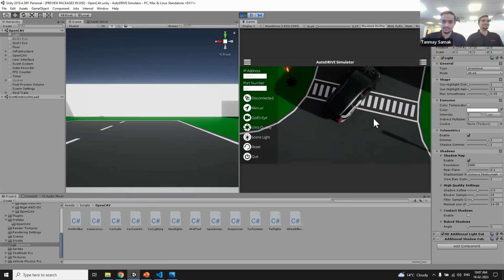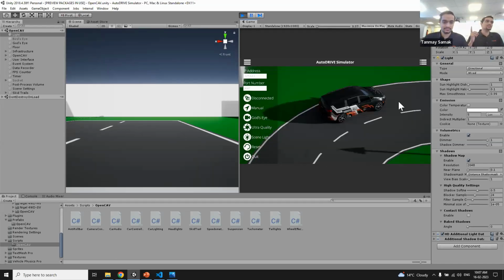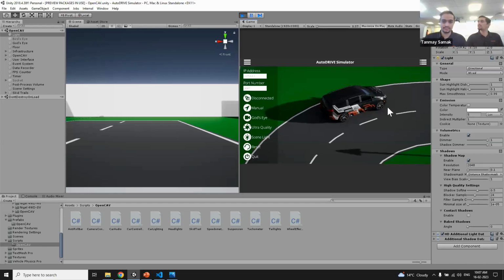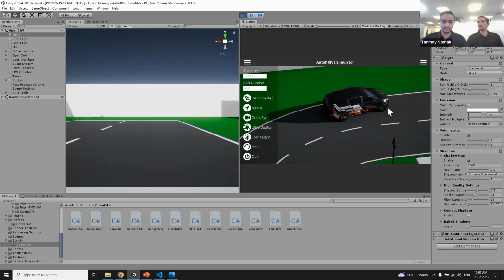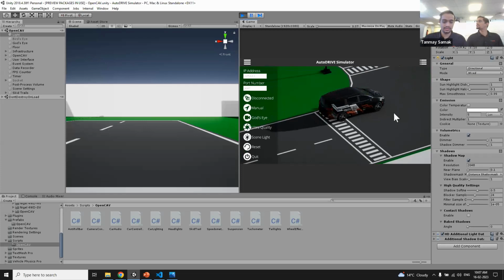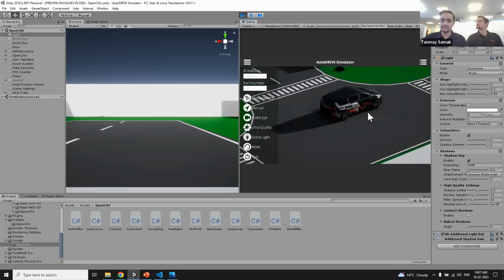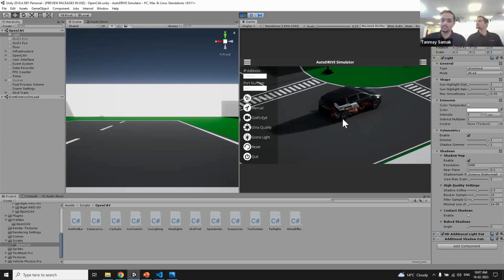If you see the front wheels and the rear wheels now, since we are hitting the throttle to the full and it's a front wheel driven vehicle, we expect the front wheels to create very high longitudinal slip, and that is actually what is visible. And even with the handbrake, you can clearly see that if I hit the handbrake, the front wheel keeps spinning until the brake powers the vehicle down, and if you still hit the throttle, the wheels will spin in place.